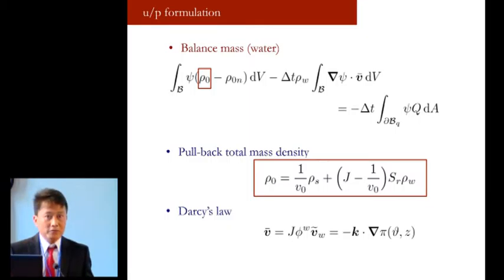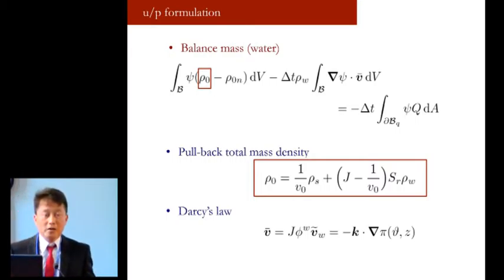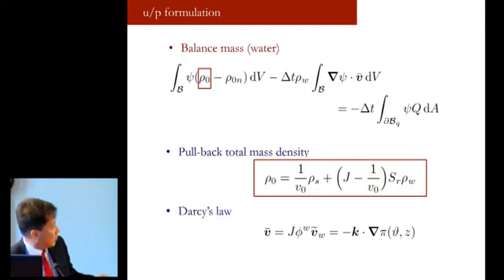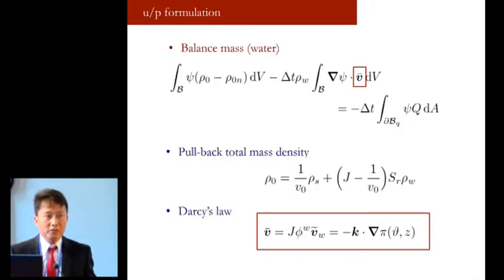Next, we have the Darcy velocity, which is given by this particular expression here, a function of the relative velocity of the water with respect to the solid. There's that Darcy velocity, there's permeability or hydraulic conductivity. We shall show that hydraulic conductivity can also be expressed for deformable porous material in terms of the solid phase motion as well as the pore water pressure.